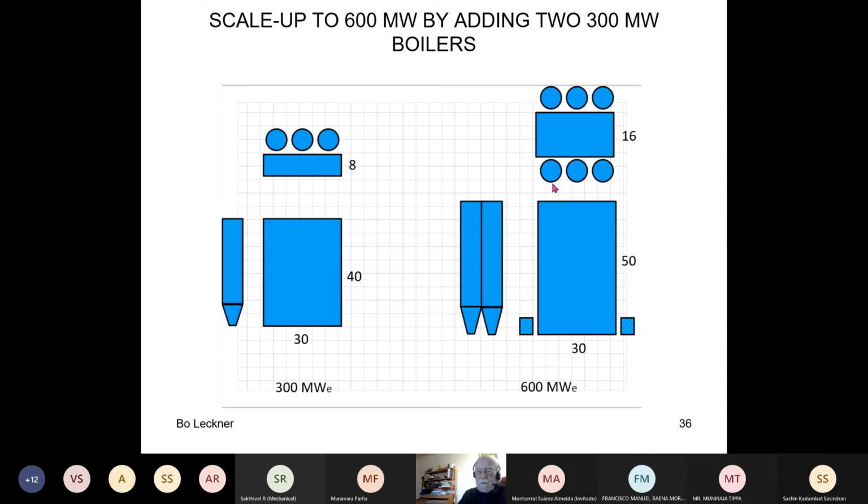And then they put cyclones on both sides. There are 6 cyclones, but this means that there was not so much space for these wing wall heat exchangers, because the entrances to the cyclones take a lot of place.